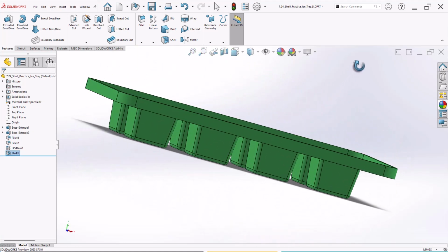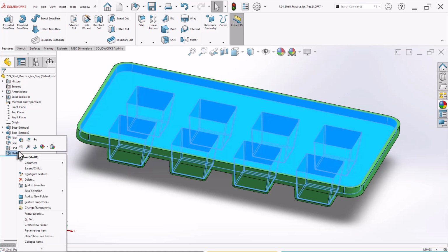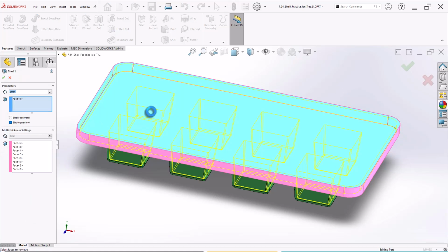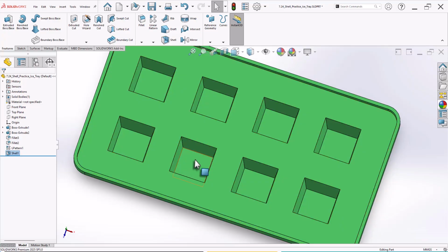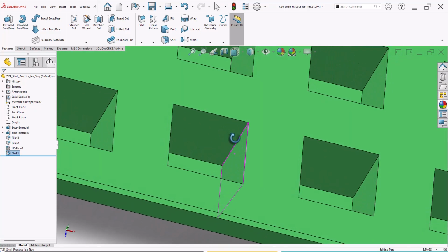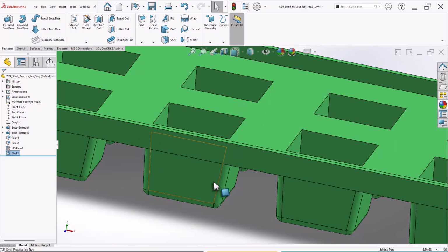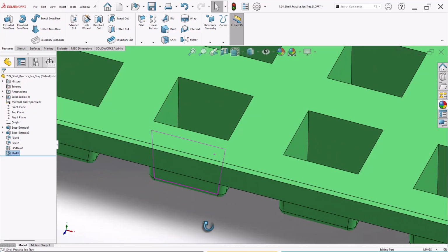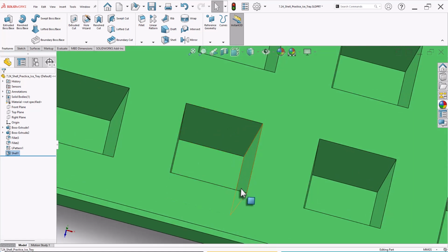Now see, this is the outcome. Now let's try to edit this feature. Here, instead of 2, let's add 2.5 or say exactly 3. Now let's try to add the cell. Now see what happened. The inside surface does not have any curvature or fillet surface, though it has a fillet outside. Because this is of 3 value and I am adding the wall thickness at 3 mm. So 3 minus 3 is 0. So it is leaving a sharp edge.